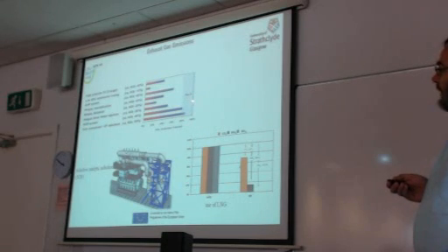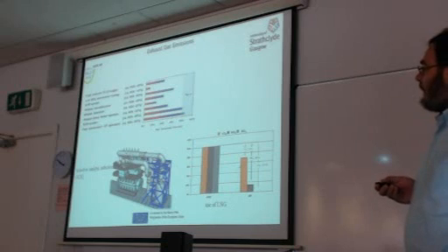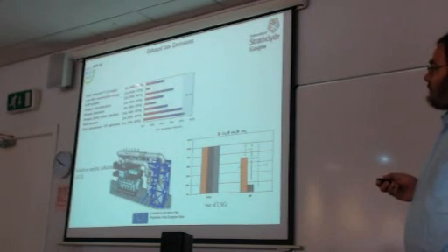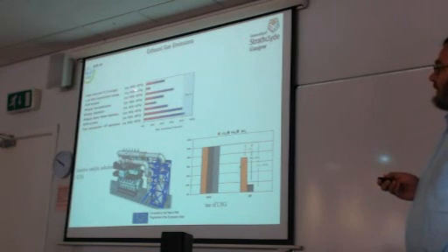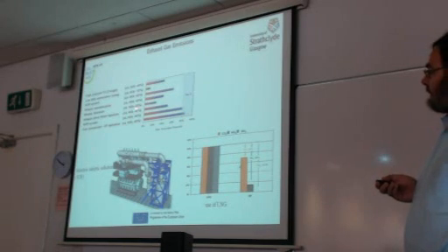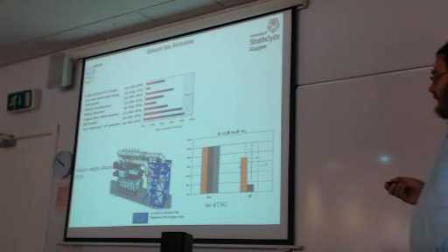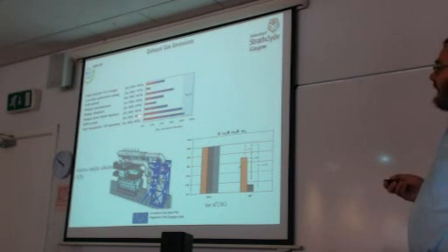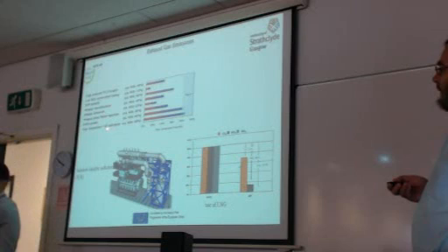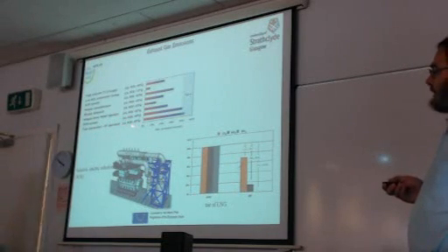So we can see here the various methods for complying with Tier 3 and also with Tier 2. High pressure or two-stage turbocharging can increase NOx by 40%. Low NOx combustion tuning can decrease the NOx by 10%. EGR system can decrease the NOx by 60%. Humidification can provide a benefit of 40%. Emulsion with water can provide a reduction of 25%. Direct water injection can provide a reduction of 50%. Selective catalytic reduction can decrease the NOx by 80%.